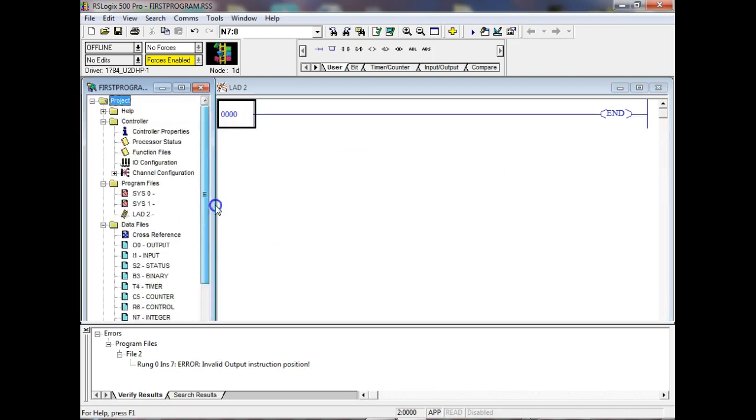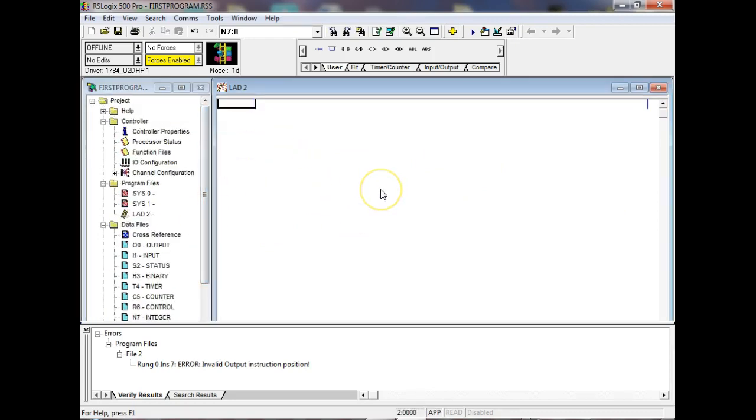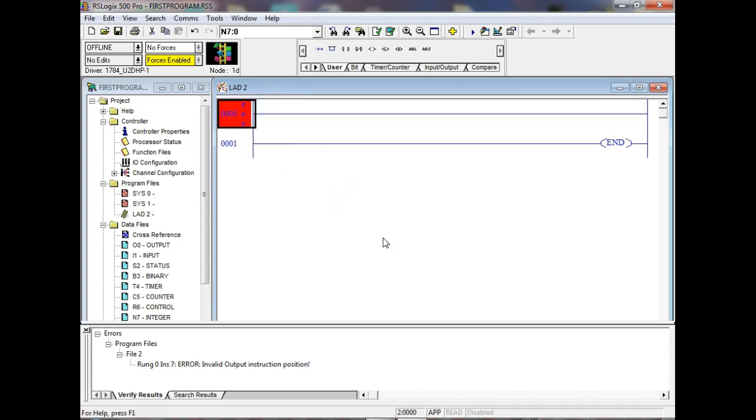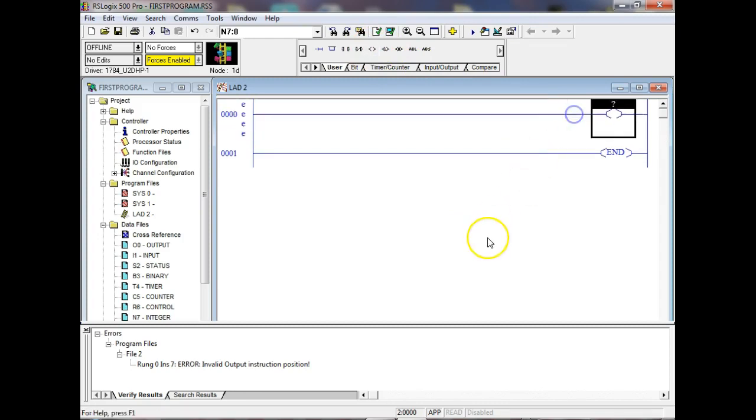So what do I do? It's going to come up and give me a wait, and then I'm going to come up here and this is the symbol for another rung, right? Can y'all see it up there? Yes or no? Yes. I'm gonna do what? Drag it down. It shows me where I can put it, right? Okay. By the way, we can have outputs without inputs, but every rung's got to have an output, right?